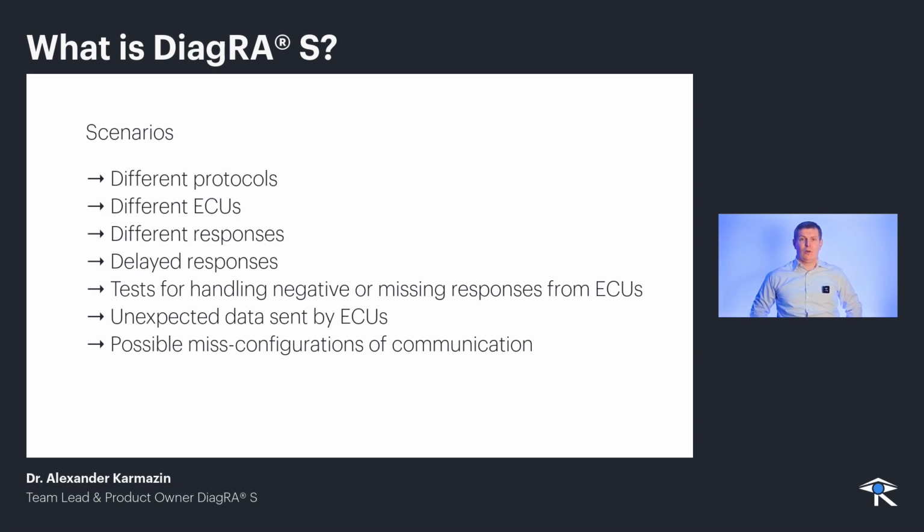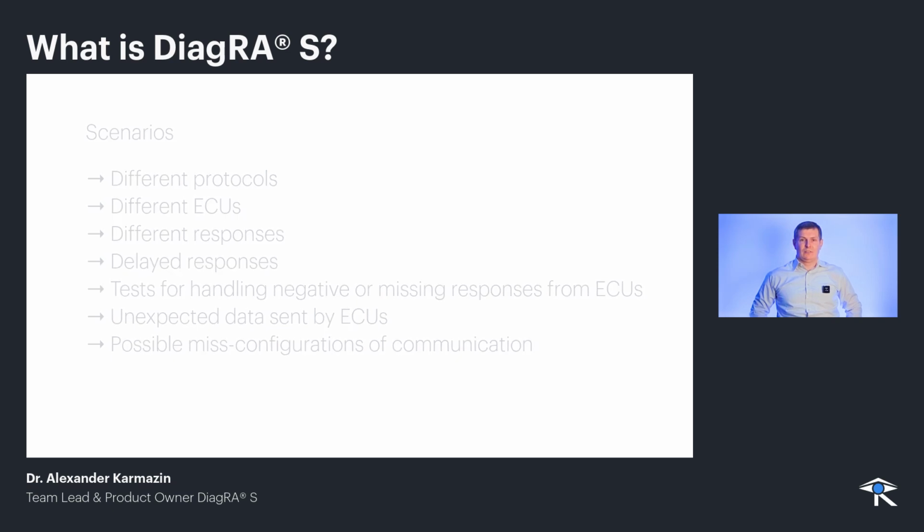Your software might also need to be tested for handling of negative or missing responses from ECUs, unexpected data sent by ECUs, or possible misconfigurations of communication. And in the optimal case, you want to assure the behavior of your diagnostic software by regression tests.